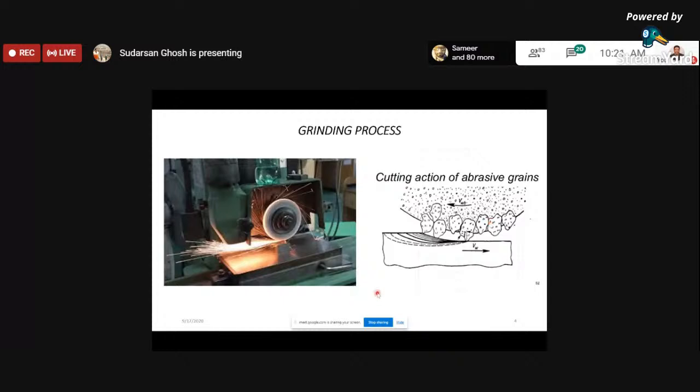So as we were discussing, sometimes these super alloys not only require machining. After the machining, in order to give them a better surface finish, sometimes we have to do a grinding operation. Grinding normally provides better surface finish and also better dimensional accuracy. For some precision components, it is very important that we do a grinding operation after the machining process. So grinding also needs to be performed on these super alloys, and this is an example of grinding which we were doing in our lab.